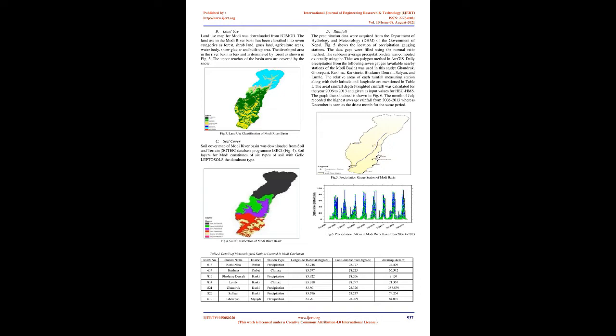HEC-RAS modeling. One of the most widely used models used by hydraulic engineers in channel flow analysis and floodplain delineation is HEC-RAS, Hydraulic Reference Manual, 2010. It is a one-dimensional steady flow hydraulic model developed by the U.S. Army Corps of Engineers. It has wide acceptance among government agencies. With HEC-RAS, it is possible to simulate water surface profiles for gradually varied steady flow and the effects of various obstructions such as culverts, bridges, structures in the overbank region, and weirs.